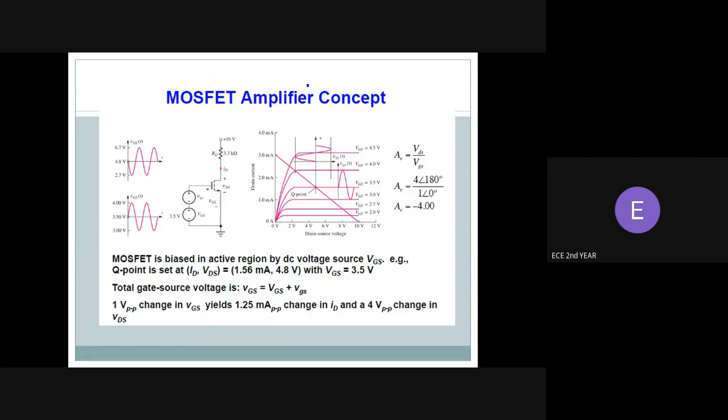The key advantage of the MOSFET is that it requires almost no input current to control the load current, when compared to the bipolar junction transistor. In enhancement mode, voltage applied to the gate terminal can increase the conductivity from the normal off state. In depletion mode, the voltage applied to the gate reduces the conductivity from the normal on state.